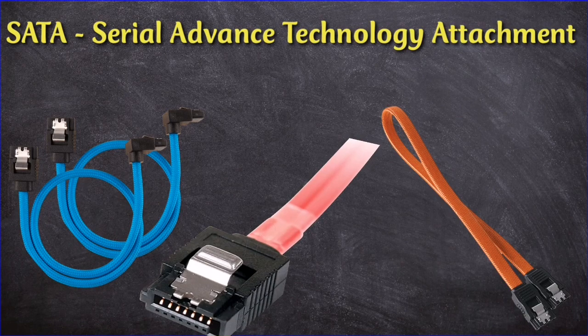Serial ATA drives each have their own independent bus, so there is no competition for bandwidth like there is with parallel ATA. They also use smaller, thinner cables, which allows for better airflow inside the computer. SATA cables can be as long as 1 meter, while PATA cables max out at 40 centimeters. This gives manufacturers more liberty when designing the internal layout of their computers. SATA interface uses a 7-pin connector.